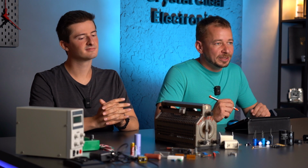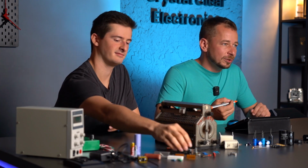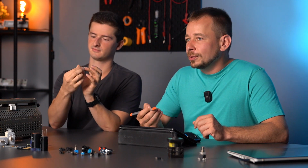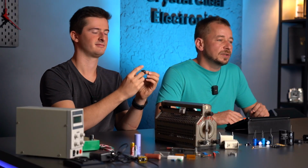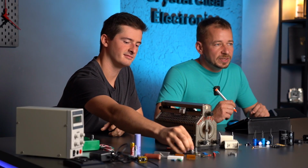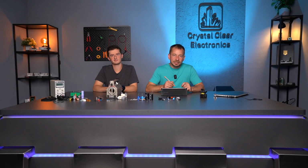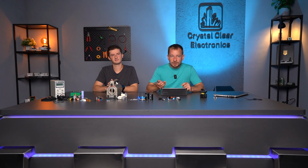A potentiometer is most often a component with three electronic leads and a shaft on which you can rotate to adjust the resistance value between each leg. I'd like to point out that the relationship between rotation and the change in resistance is linear for most types, but for many types, it's different, for example, logarithmic. So when buying a pot, it's not enough to know its value and physical size, but it's also worth paying attention to its type. It can really trick designers.